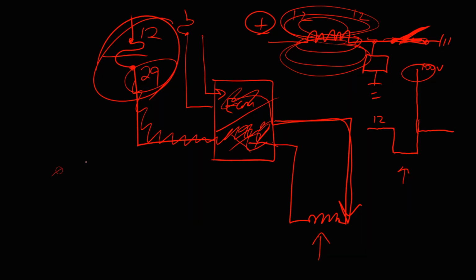And the problem started when they put a crank sensor on it and a crank pulley. And on that case study, the crank pulley was incorrect. It was an aftermarket part. It was the right part, but it was just slightly off. It wasn't pushed in as far. And the sync notch for the crank sensor, so you got a crank trigger wheel with all these notches, right? Well, you got one notch that's unique. Let's just draw it as the circle. That unique notch was not being recorded properly because it wasn't the right fit. And so the car never started when they put that in. And so then they created that problem.